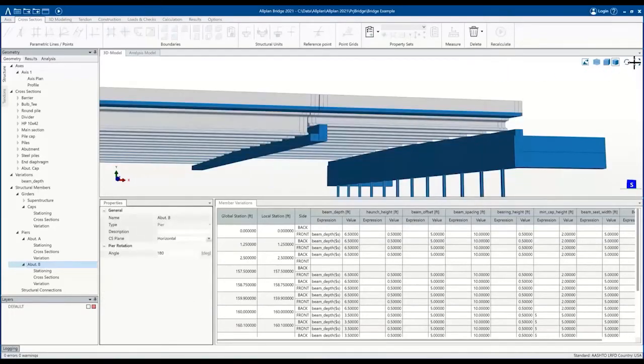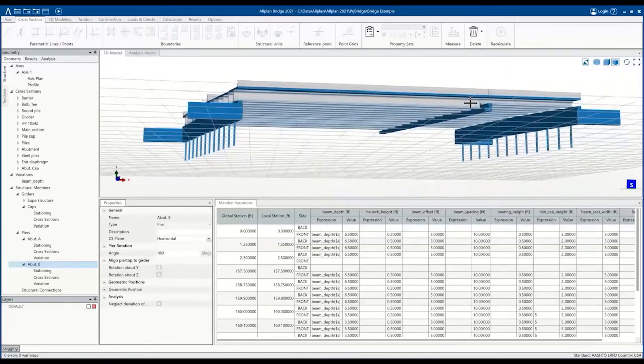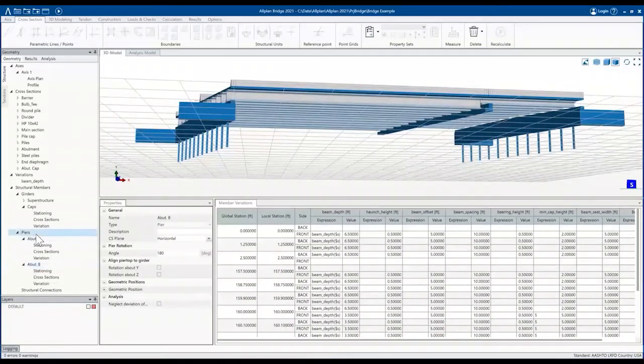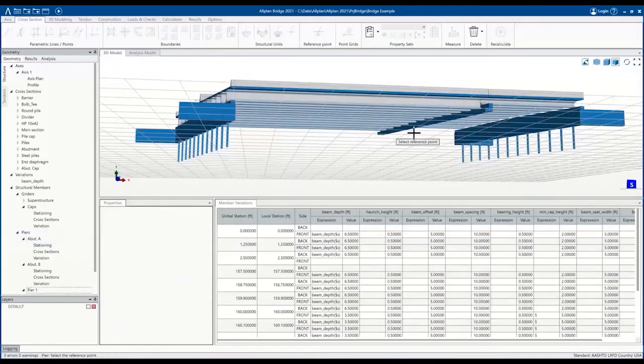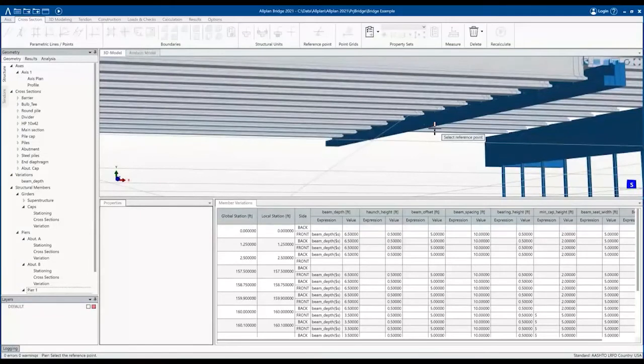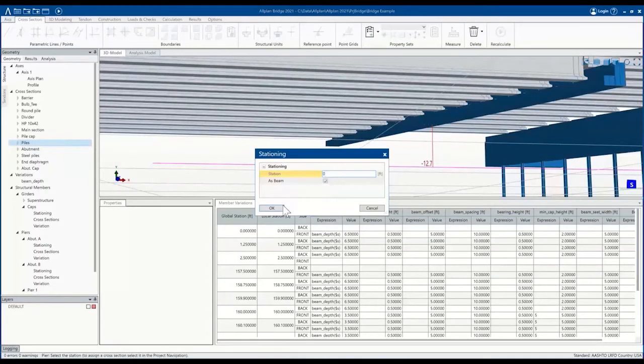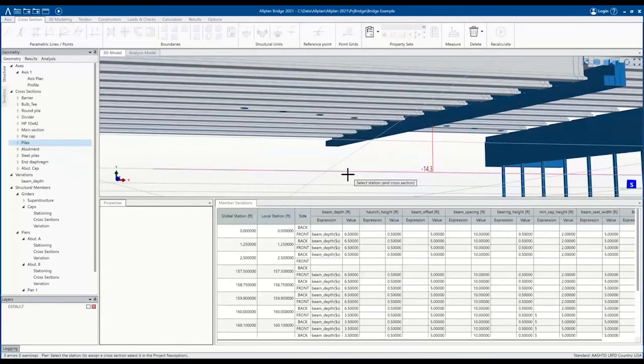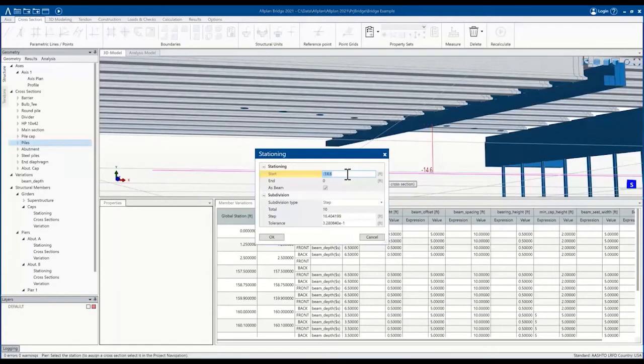Calculate. And again, when we use these copy paste functions, they aren't quite like a CAD copy paste function. That abutment is tagged to the station and to the superstructure elements. So as that station changes and as the superstructure changes, that abutment is going to move around along with them. If we change the entire location of the bridge slightly, shift it over or change the alignment a little bit, it's going to follow along. You will, of course, have to go check that the geometry that you set up initially is still valid, but the continuity is there.